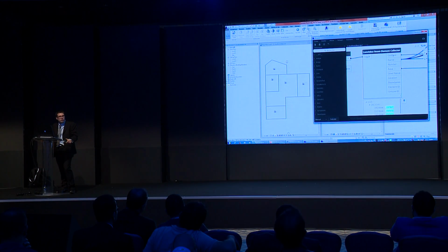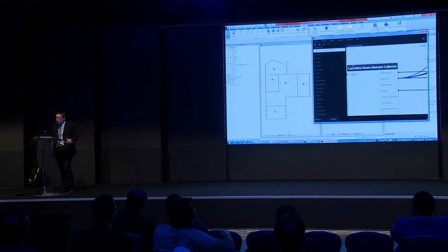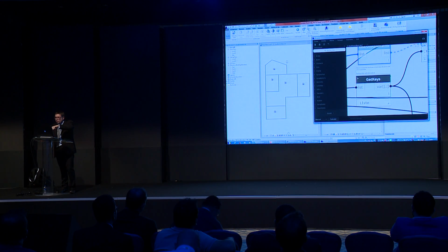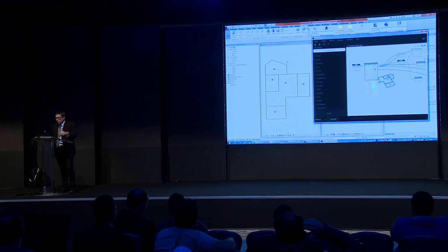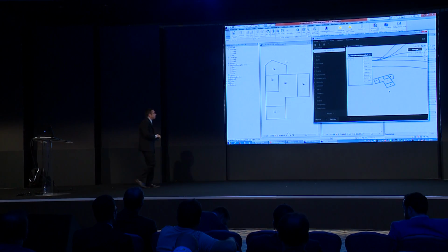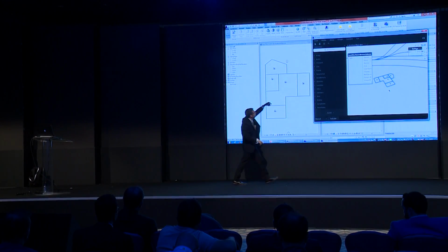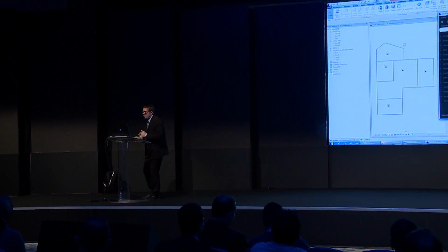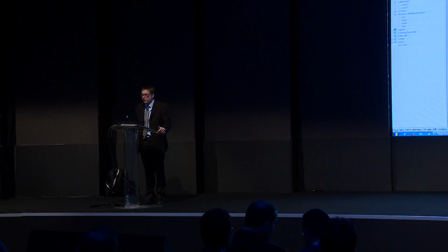this package here, you recognize a package because you've got some sheets behind it. A Dynamo node doesn't have sheets behind. And this package, as you see, creates for you in the Dynamo interface the shape of the room, and also gives you some information about name, area, and level name, and you've got the result here. You can do this with basic features in Dynamo, but using this package it is already done with one node.